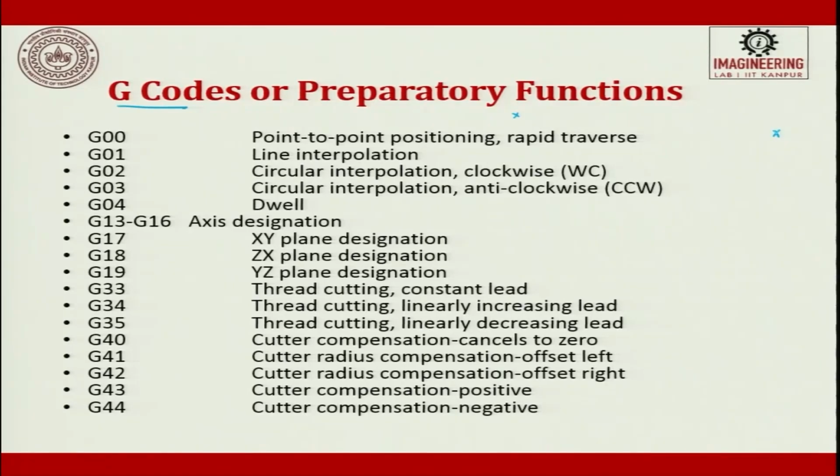The only control is the starting point P1 and P2. So, it is point to point control. We are least bothered about the path it takes and we do not do any machining. So, because of that the feeds are running at infinite speeds, that means to say it is going at its maximum feed rates.